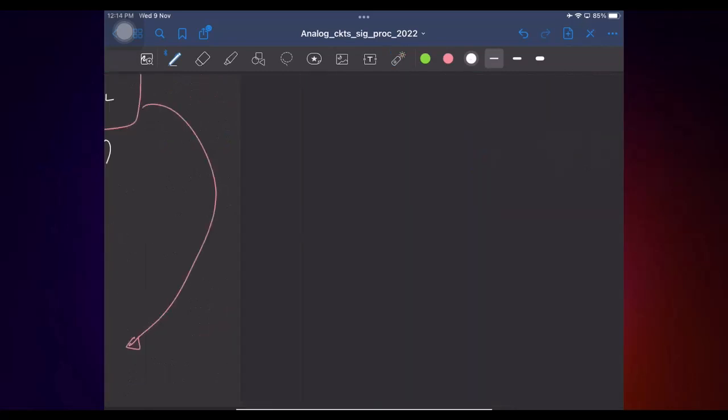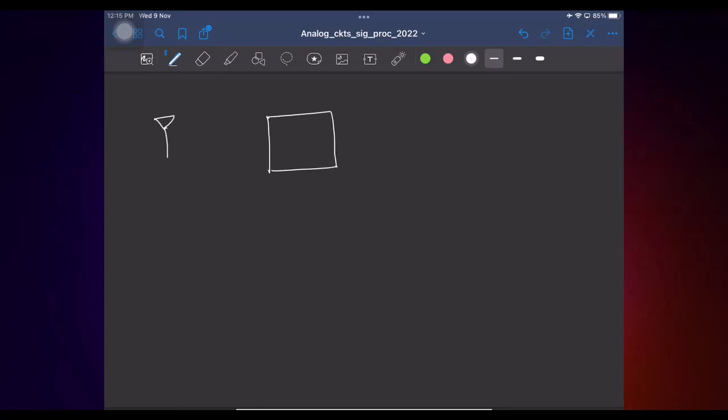And yeah, this idea of delivering the maximum power to the load is very crucial, especially in RF designs, because say your entire RF receiver you can make in one chip, but finally you need an antenna that will be an off-chip component fabricated separately. You can think of the antenna as another transmission line that is picking up signal from space, right? So again, this will be designed to have a characteristic impedance of 50 ohms. So let's say you will connect it through a 50 ohm cable and connect it to this. And let's say the input of the receiver will mostly be a MOSFET, something like this.